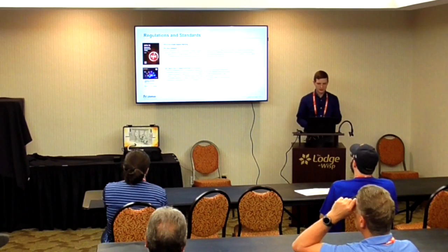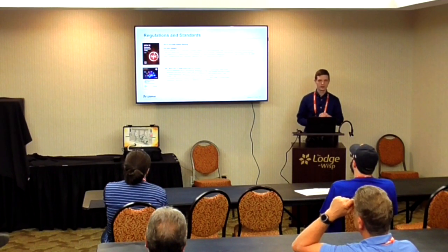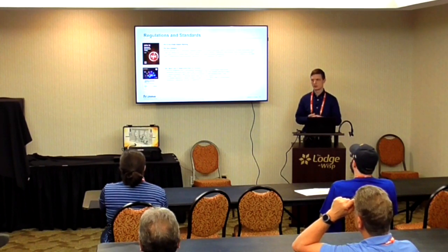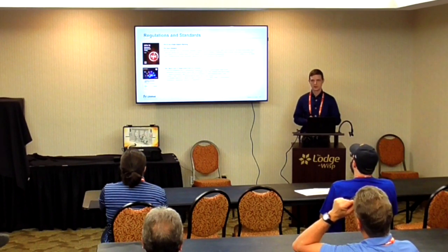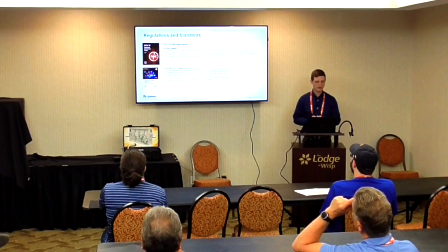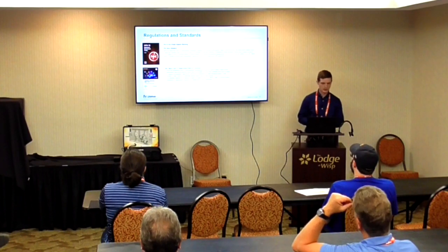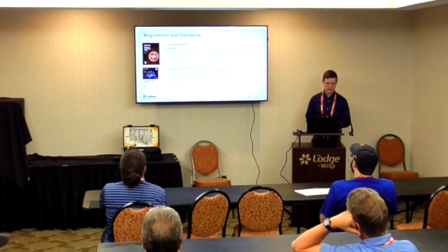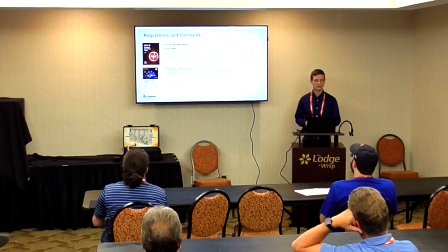When you look at the electrical codes, this would be things like the NEC, or CSA if you are in Canada. They are in place to provide a minimum bar of safety. So this is a minimum requirement. This should be pretty much your electrical Bible. There are still some better standard industry practices that you can do out there, but this would be your minimum. As part of that minimum, I have actually gotten some articles pulled up here, specifically 110.16 from the NEC, which is for labeling.